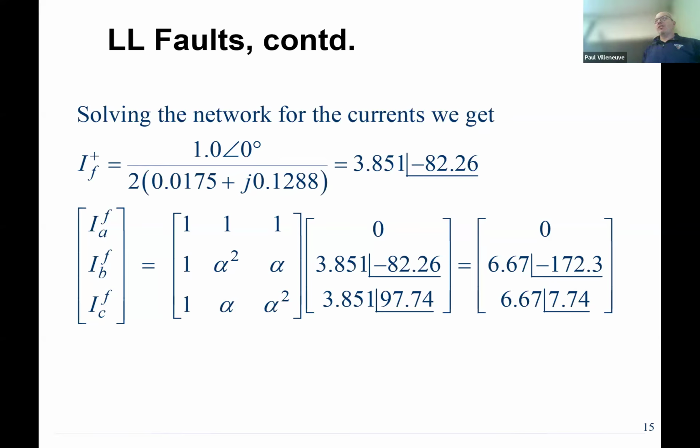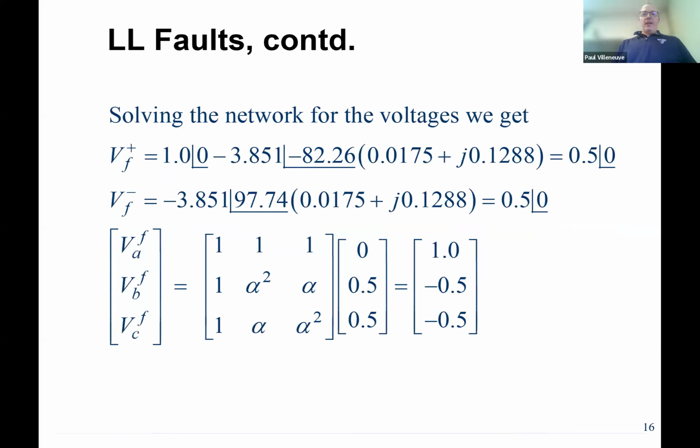Okay? Questions on the line-to-line fault? Just take the positive and negative sequence diagrams, put them in parallel, and do your calculations. Any questions? All right, and then we can actually solve for the voltages.